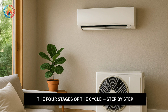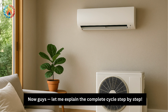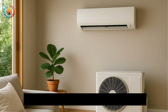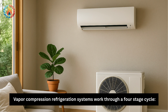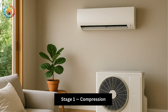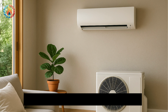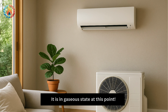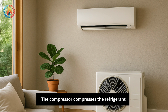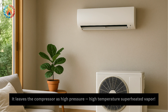The 4 stages of the cycle, step by step. Now guys, let me explain the complete cycle step by step. Vapor compression refrigeration systems work through a 4-stage cycle. Stage 1. Compression. Refrigerant enters the compressor as low-pressure vapor. It is in gaseous state at this point. The compressor compresses the refrigerant, raising its pressure and temperature significantly. It leaves the compressor as high-pressure, high-temperature superheated vapor.